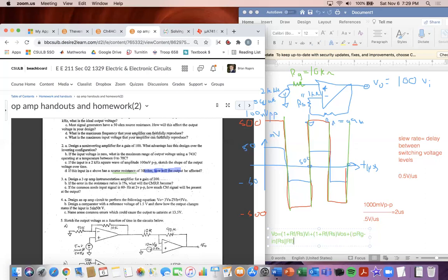And then that's going to be multiplied by our value, which would be the gain, because that would be the voltage. So VP minus VN times the gain, which in this instance would be 1 plus RF divided by RS. Okay, we know how those three equations now work. And so now that we know all that, we can plug in our values. So our output voltage is going to be 1 plus 99K divided by 1K.